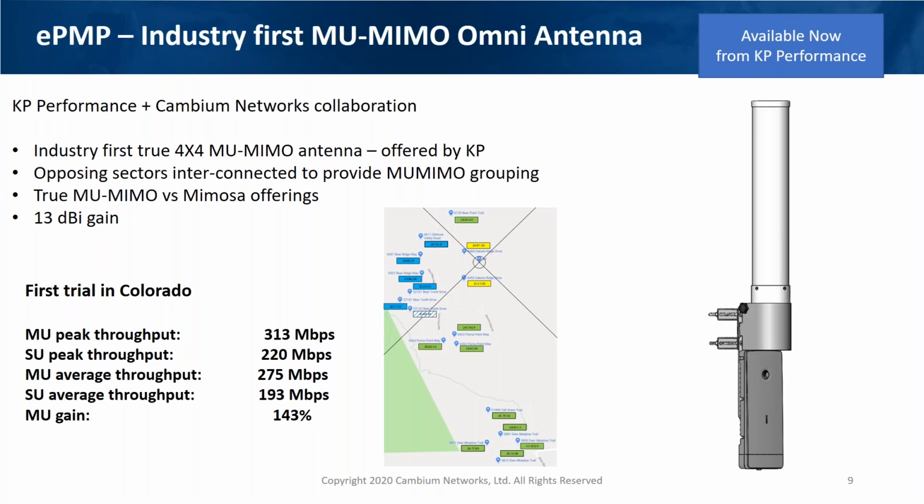They certainly have their place, but you always need to make that trade-off between what that's going to do to my noise floor, because I'm going to be transmitting now in 360 degrees, and also what it's going to mean for my noise floor for my active subscribers, and what other noise am I going to pick up because I'm now listening in 360 degrees. But it's a great option and a good thing to have in the toolkit.